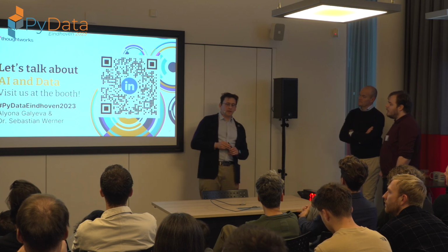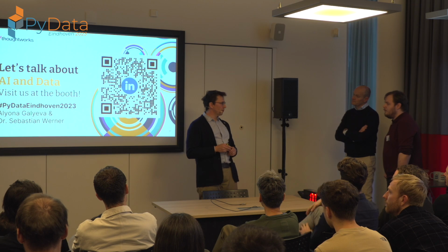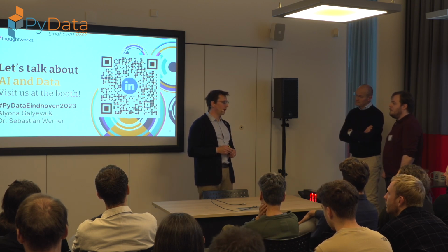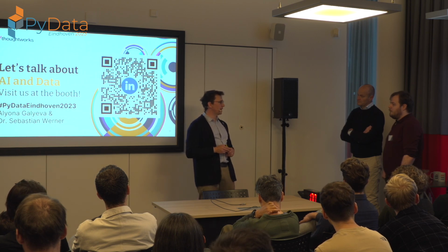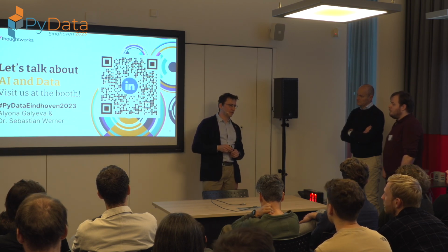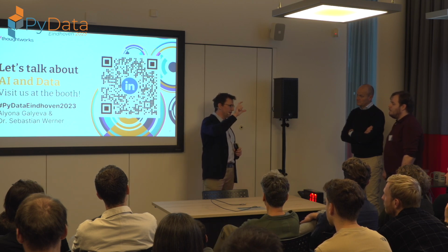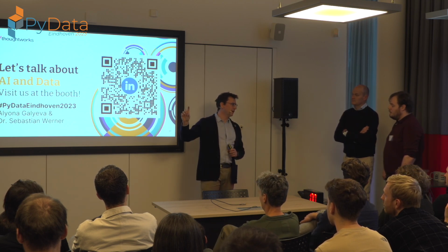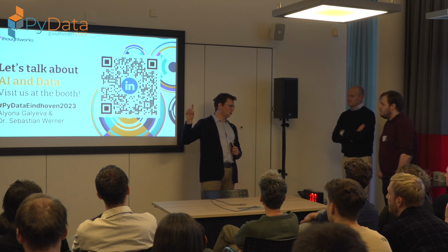Okay. In order to forecast the, let's say, achievable accuracy in a forecasting model, I would highly recommend to first look into understanding the uncertainty that comes from the sensors itself. If you have a 5% uncertainty in the measurement that initially goes in, it is extremely unlikely that you will ever be able to produce a model that is better than this 5%. It sounds so simple, but please don't forget that.